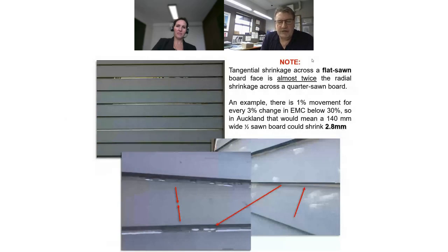What's more important to everybody watching today is that Brands says don't do it. And the reason Brands says don't do it is that on a windy day, when those boards are moving just a little bit, air pressure can push up behind there, and it helps aerate, and it helps keep your building dry in the cavity behind. So it's not necessarily a bad thing to have those gaps, right? But if I can get one thing across, please don't gap your weatherboards with sealants and all of that sort of stuff. Let them breathe.